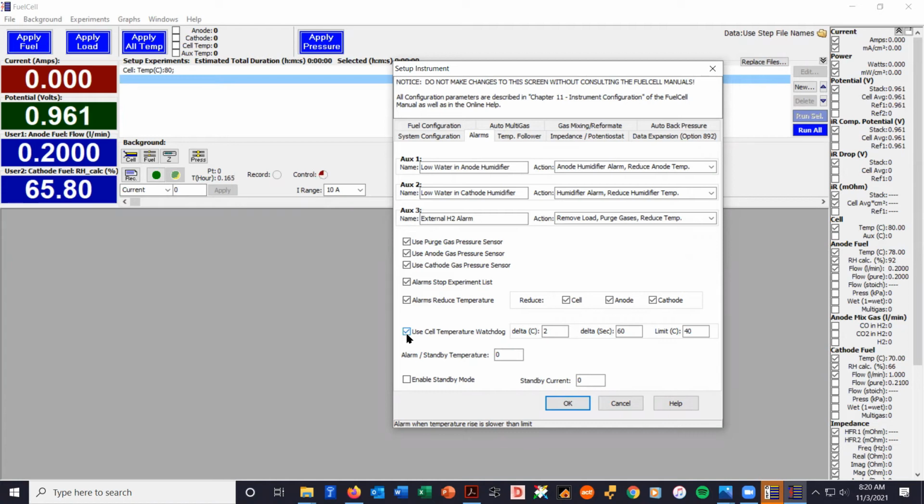And we apply heat, where we try and heat up the cell, and the cartridges get very hot, and we end up with a dangerous situation, either a potential fire issue, or at a minimum we end up scorching the bench top, and also you don't want someone to pick up a hot heater. And so they said, can you make it so that if the temperature of the cell doesn't start to rise, you can stop the heating process? So it's kind of an extra safety feature.